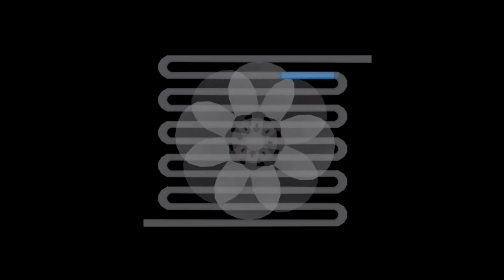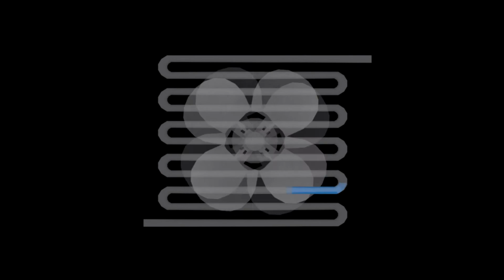Evaporated refrigerant will leave the evaporator to the suction line of the compressor, and the circulation of the vaporized refrigerant will continue until the desired temperature obtained, which is detected by the sensing bulb fixed at the outlet of the evaporator.